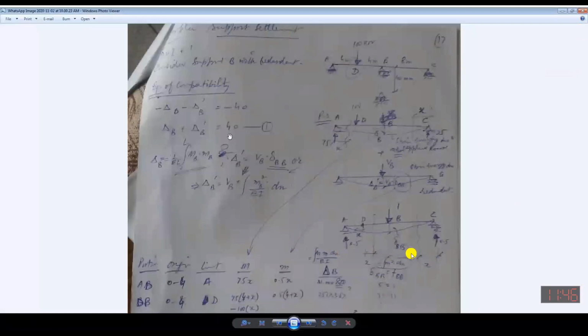Yes, you can use any other method which is available under the umbrella of basic mechanics. As I have told you, the table is available, ready-made, for rotation and deflections, and you will have to synchronize the tabular values with your actual structure. If the same formula exists in the table and your loading condition is the same, then you can use it directly.